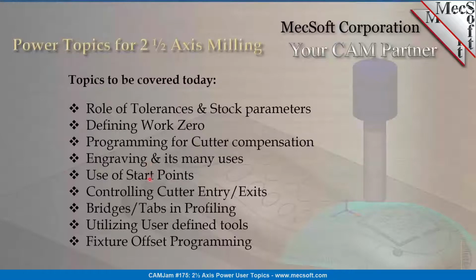And then we'll be talking about start points and how to control start points, and also how to control the cutter entry and exits during machining. We'll also be going through bridges and tabs and profiling. And then user-defined tools, how we can create and utilize them. And then finally, fixture offset programming. It's quite a lot of topics to cover, so without any further ado, Uday, you want to take it away?